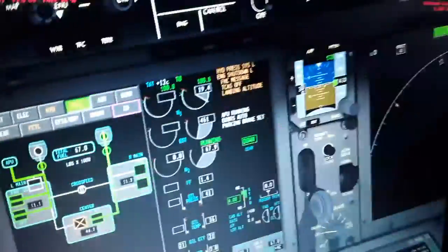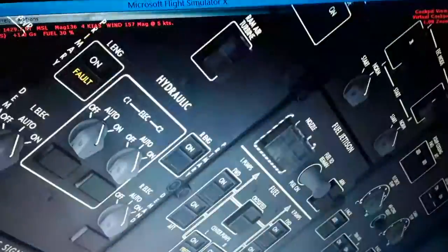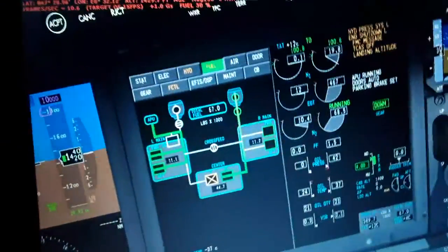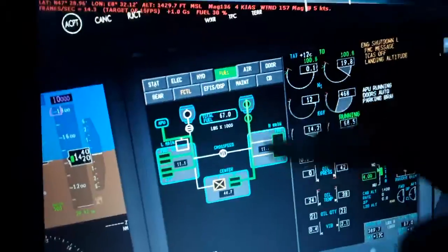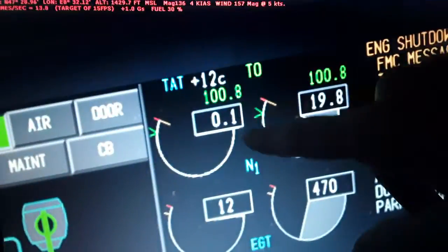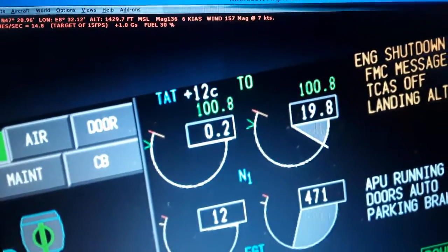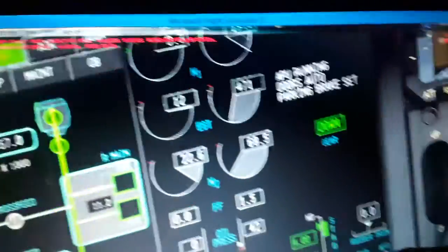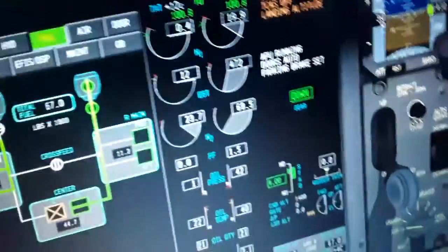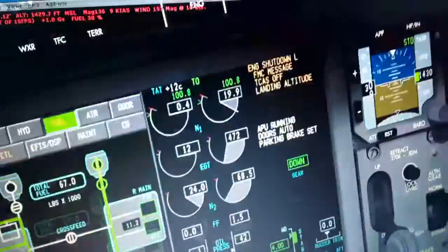While the left engine is still off, we're gonna come here to the other side engine, the left starter. So we're gonna start the left engine now. You're gonna see the reconfiguration. We have the fuel flow here to the engine. The N2 is increasing here to the high pressure compressor stage, while the low pressure, low speed stage is still slow. The exhaust gas temperature is very low, while the other is 471. The fuel flow is still 0. We only have some oil pressure here. As you can see, 24%. We are in a good position.